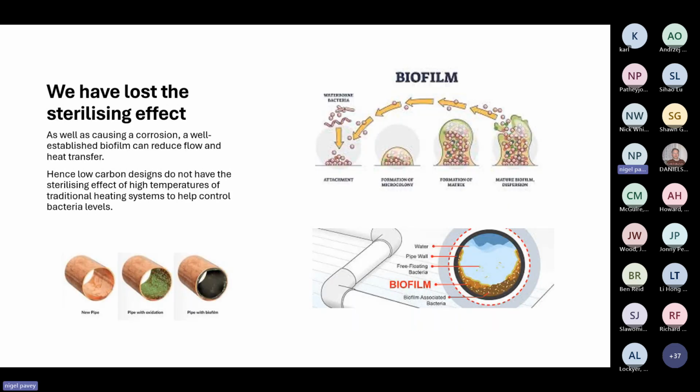So hence my heading on the next slide: we've lost the sterilizing effect. As a steam engineer many years ago, I never worried about bacteria because at 120, 140 degrees, it cannot exist. But with low carbon designs, you've got to be careful. They cause corrosion and biofilms, they reduce flow, and particularly they reduce heat transfer.